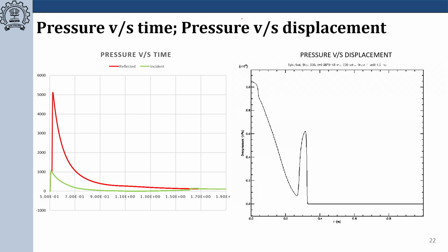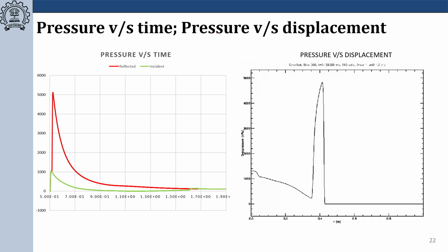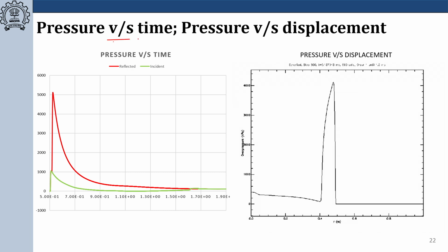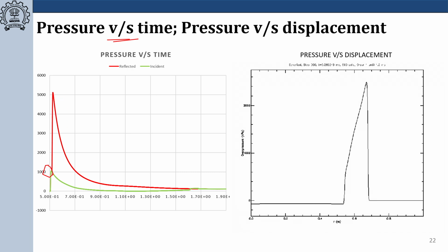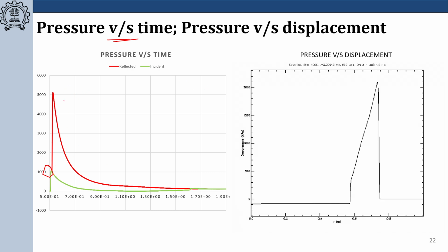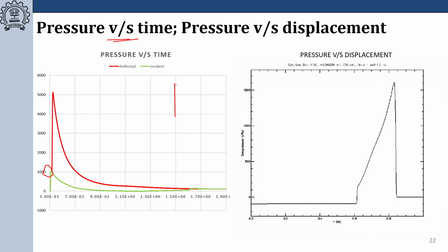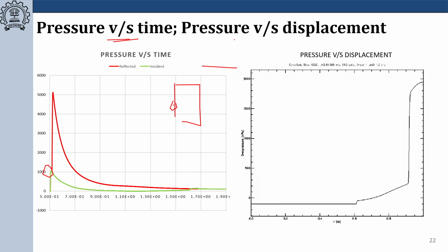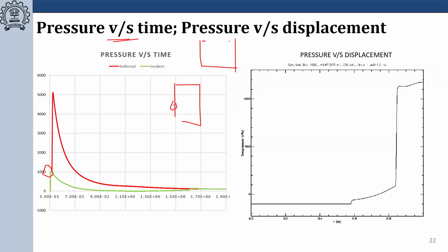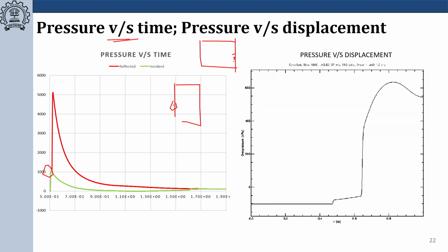And when you extract the data, say some point reflected data, the incident pressure I can extract, since there is no obstruction. And if you want to generate the reflected pressure, either you obtain the data on the boundary, or you give a reflected boundary in the domain, and at the reflected boundary you keep your target point and get the data.